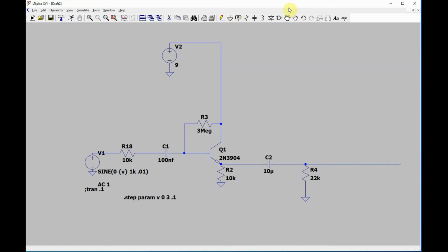One way to stop or block that sometimes is putting in a little base blocking resistor, like right there, like 1K, or right here, or even on the output. It's good, at least as far as preventing oscillations from further stages, to add a little bit of linear resistance. I usually put 1K there.